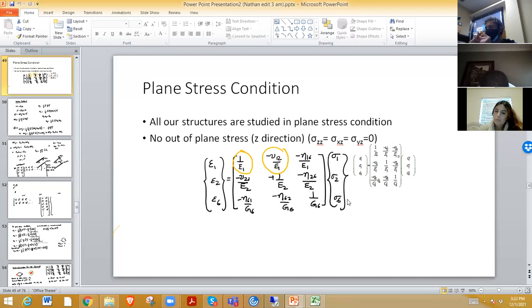We want to apply torsional spring, and an alternative is, I just think it may be very easy to do in SAP 2000. I think you can try both, whichever one is easier. Because in SAP, there is a direct method. You can go to the joint, you can put a spring there. So you could try both.